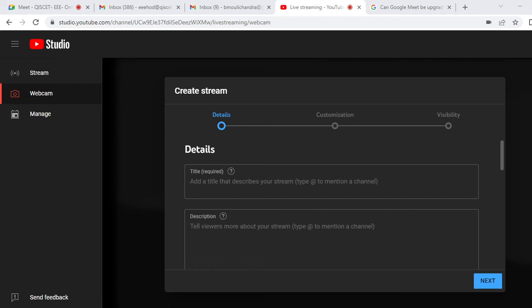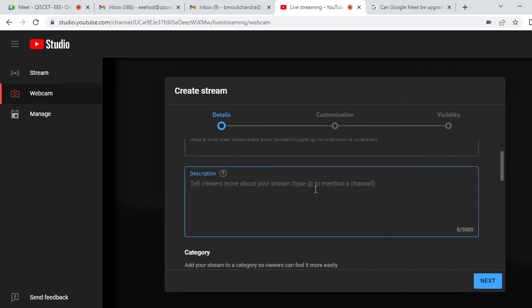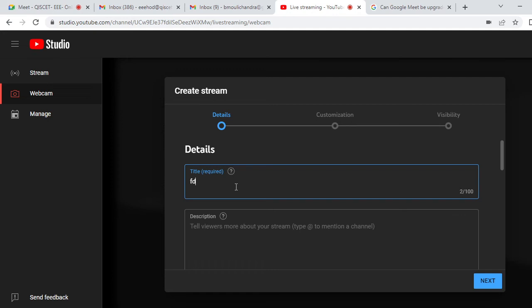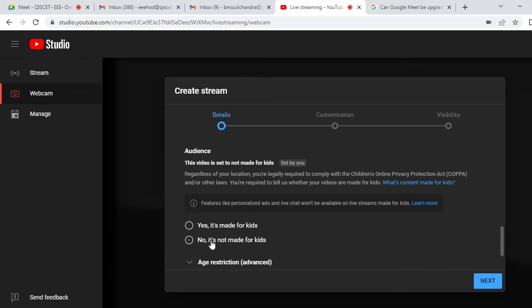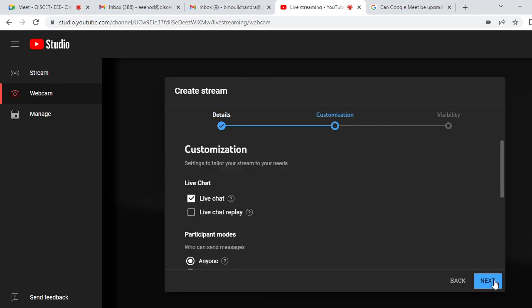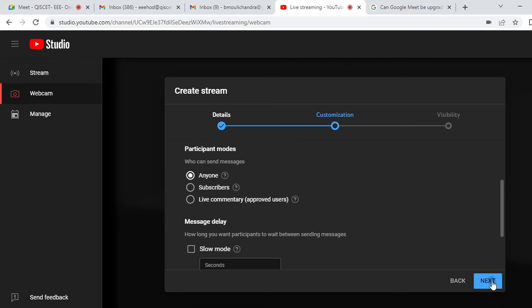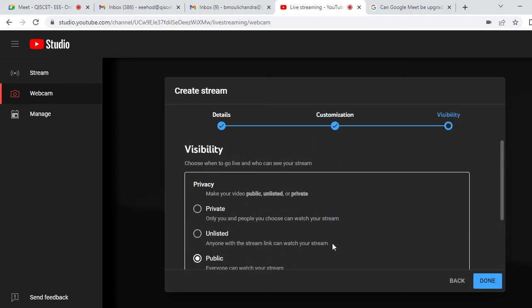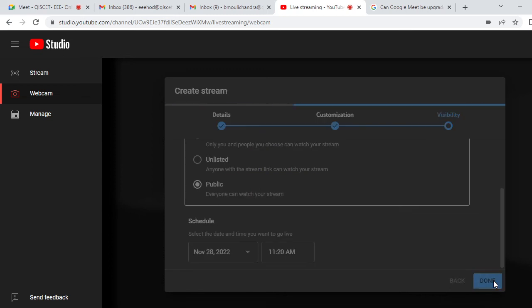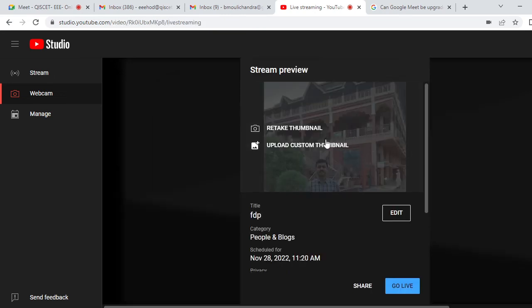But at the same time, we can manage this reactive power as well as the active power loss as well as the voltage stability by means of different configurations. Here in a 3D plot we have shown, for a particular configuration, what is the active power loss, what is the reactive power loss, and what is the voltage stability index. This axis gives you the active power loss, this axis gives you the reactive power loss, and this height gives you the stability index.